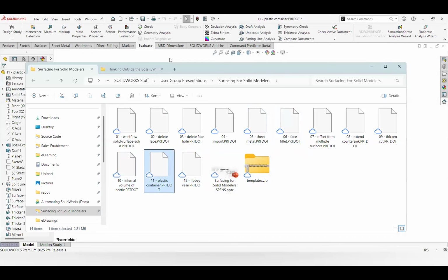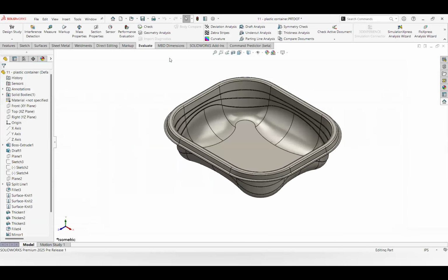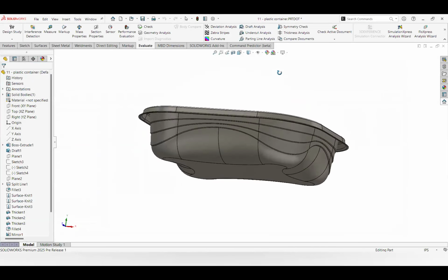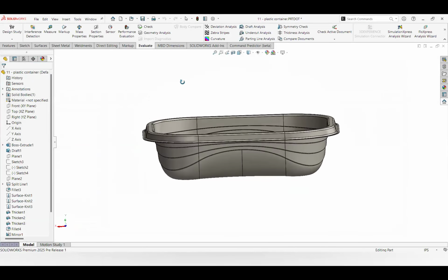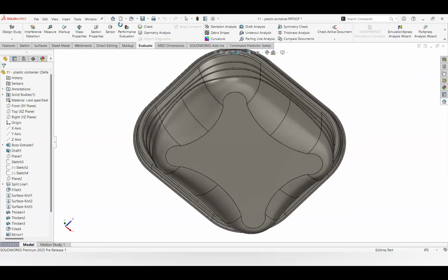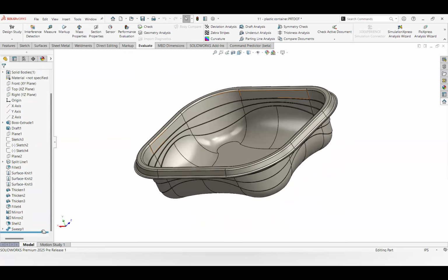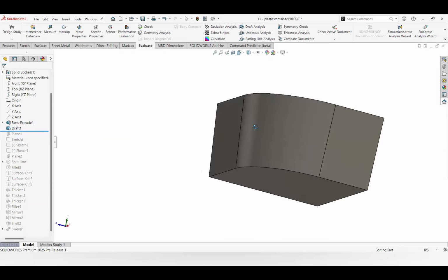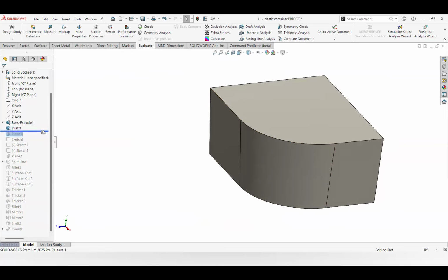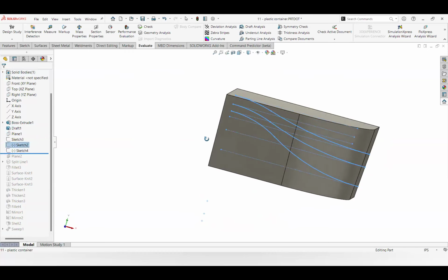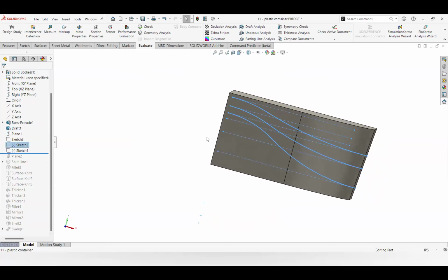Definitely a strategy when you're dealing with contoured shapes like this: absolutely use symmetry to your benefit. So this thing really has quarter symmetry. You'll see in the model, the way that it was done is just a quarter. It's just an extrude with draft, nothing terribly exciting. But I've got some sketches over here that I want to use to represent what I want on the side as those curves.